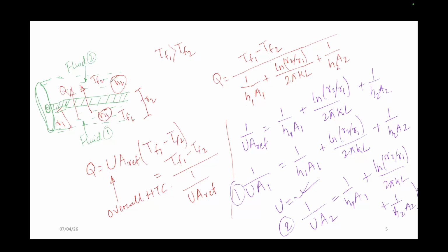Another thing that can happen in a heat exchanger is this: the water that we find in our households contains certain minerals, scaling factors and many impurities. If you take a bucket of water and keep it for 1 week, you will see certain colorful particles settle deep inside the vessel, right? So what is this? These are actually scaling or fouling effects.